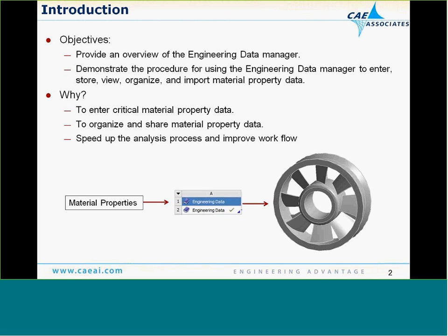Why learn this? Well, the most obvious reason is because you have to enter material property data for your analysis, but also use the Engineering Data Manager to organize your material data and to share your material property data. You can store data in material libraries, and those libraries can be shared out to other users, or you can use them in other projects. The goal is to speed up your analysis process and to improve your workflow.